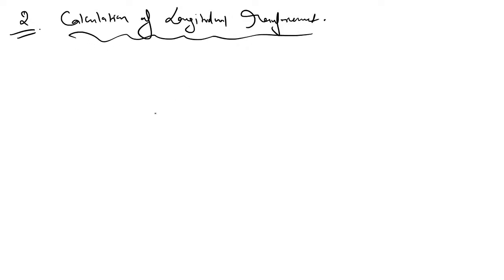Is it clear? So how are you going to calculate your longitudinal reinforcement? First step is to calculate the value of Mu. So Mu equivalent is Mu plus Mt.